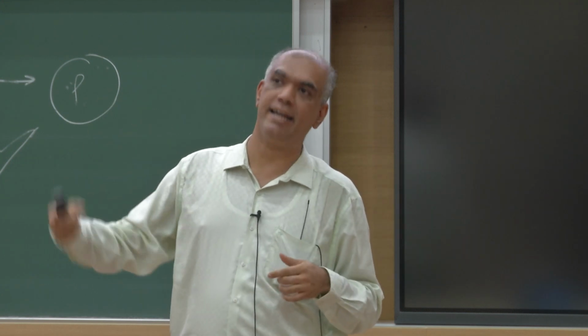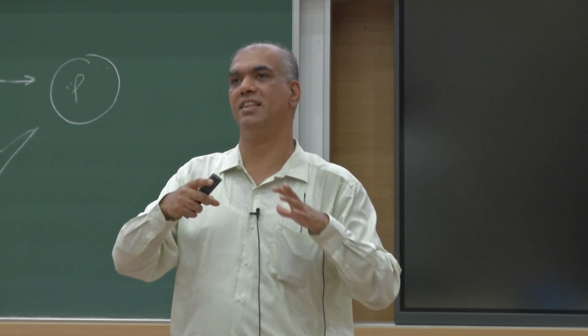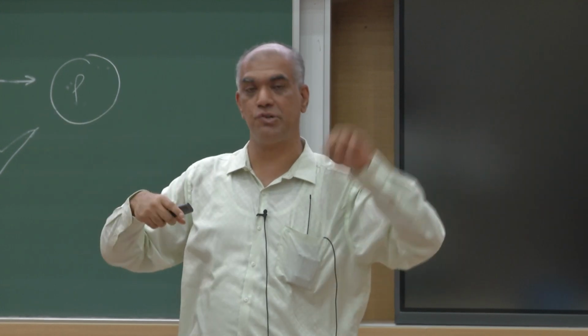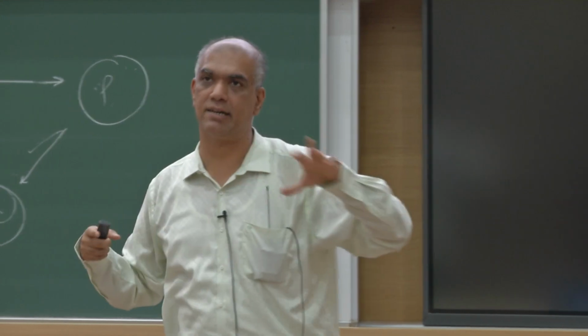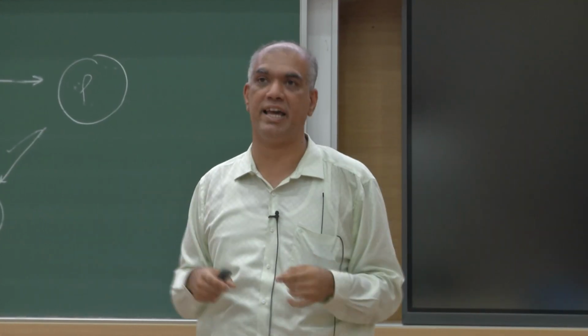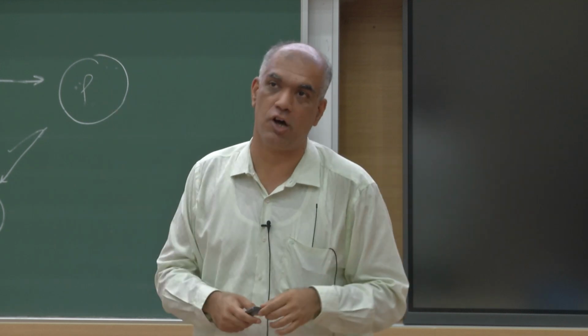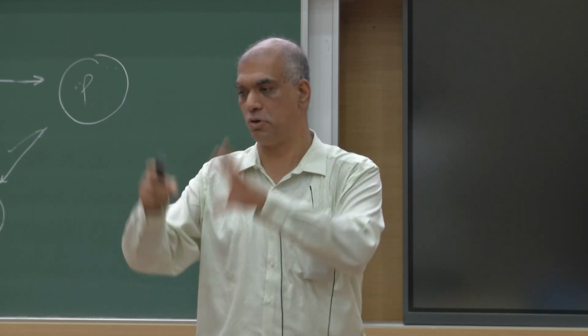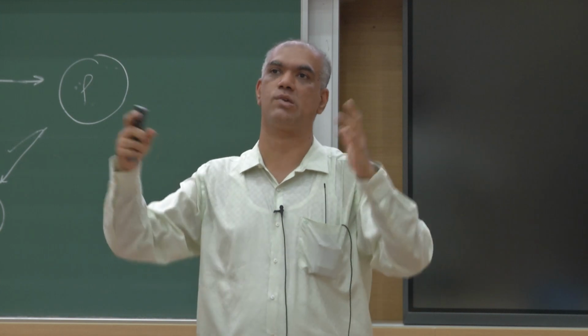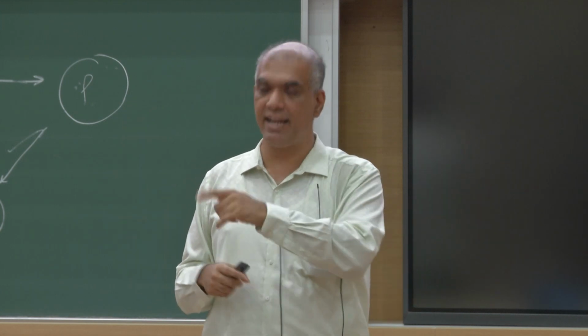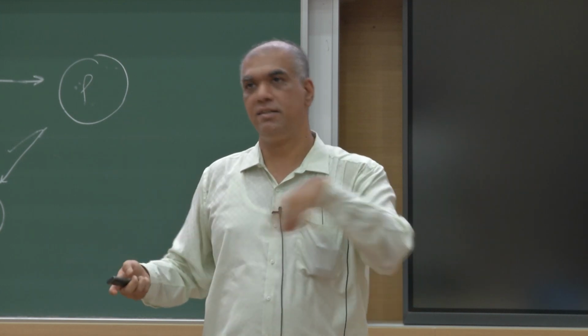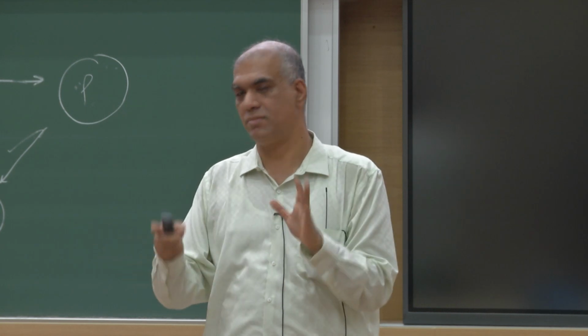If a HAZOP had been done, right, what you do is, in the real industry, you would have a smart set of guys. You would have a mechanical engineer, an operator, a couple of chemical engineers, and sit together and go line by line. Of course, we are doing a simulated HAZOP, but it still makes a lot of sense for you to take your crucial equipment, say an exothermic reactor, and look at every line in your P&ID, and 6 of you sit together and say, what happens?